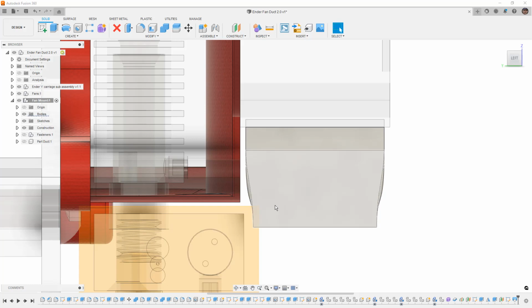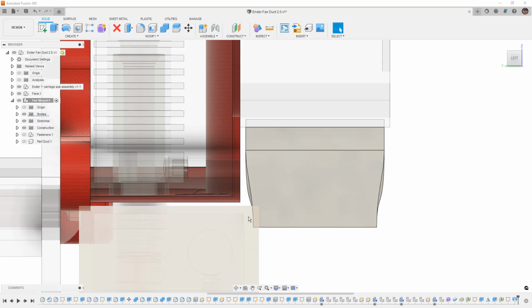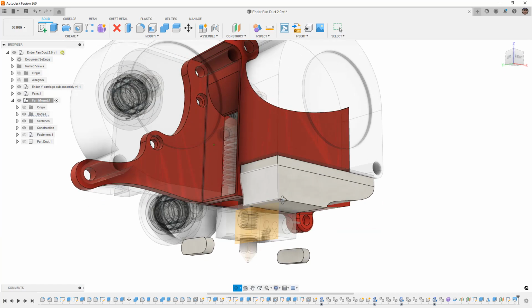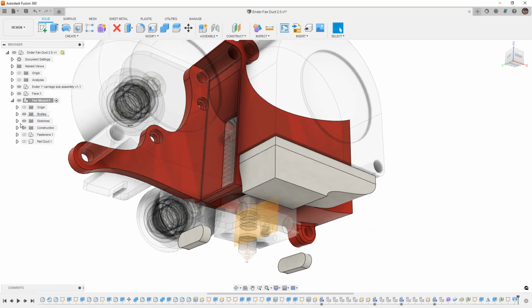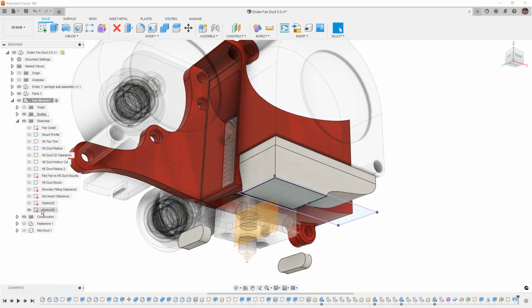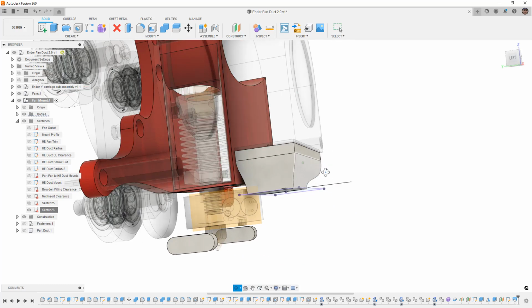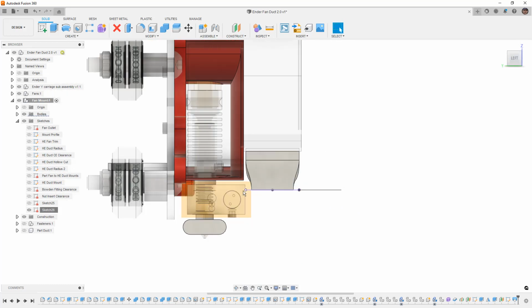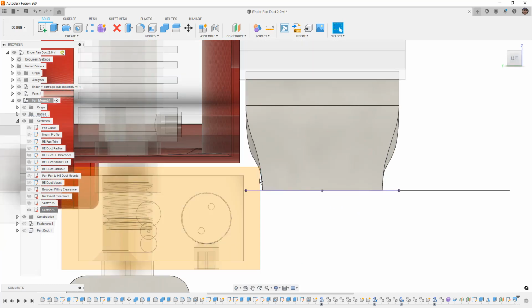Now, we do need to remember this is the inside shape. The inside shape is obviously not the outside shape, which means that we do need to still have material here. So that means that I need to make this a little bit smaller. It's very easy for us to do. We'll just go back to that last sketch. We'll show it. We'll right-click and show its dimensions. And then I'll change this 1 millimeter to a 2 millimeter. We'll just neck it down a bit more, and that'll give us an additional 1 millimeter of clearance here.